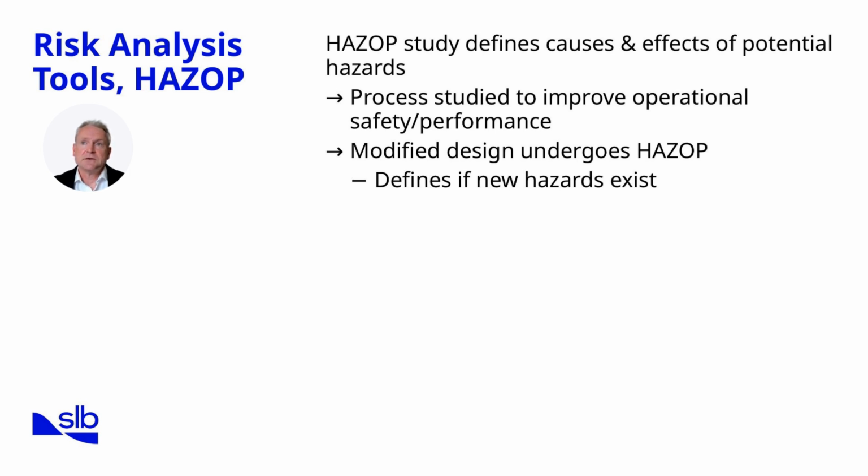This iterative approach is important because drilling and completions projects are rarely static. Designs evolve, and so must our risk assessments. The HAZOP provides a repeatable structure for that re-evaluation. In simple terms, it acts as a living process for risk control. Each time the design changes, the HAZOP provides assurance that safety and operability remain intact. With this understanding, we now turn to the people involved in making a HAZOP successful, the standard HAZOP team and their defined roles.